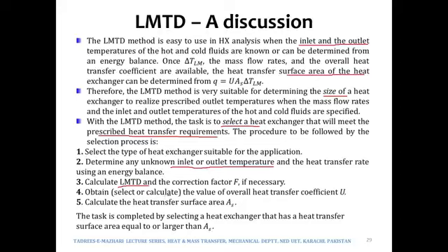Then obtain, means select or calculate, the overall heat transfer coefficient, and then using Q is equal to U A LMTD, calculate the surface area.